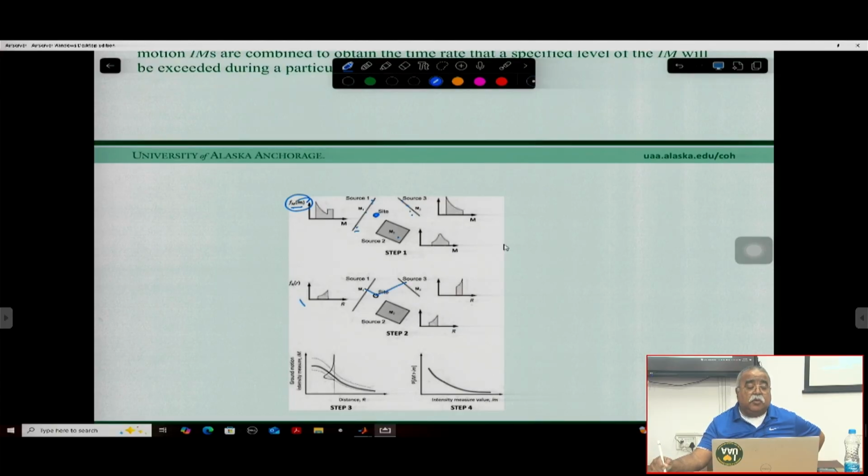So that we will try to calculate. So this is the contribution or probabilistic contribution of the distances, and then we can take these two all together and create a probabilistic hazard map, and then we can calculate the probability of magnitude to be this much and probability of distance to be this much, then calculate the spectral hazard map of this part. So that is what the probabilistic seismic hazard is.